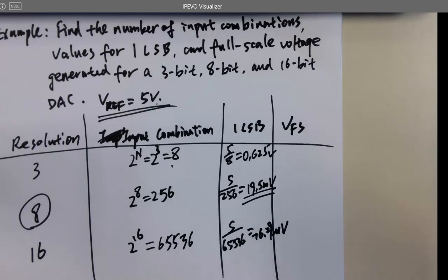Definitely, yes, microvolt signals. Not really common, but yes, from the sensors. Some sensors output microvolts, but they usually pre-amplify everything before you make the connections, since they're not asking customers to design the amplifiers. They put well-designed amplifiers on the board and sell it to you with the sensors.